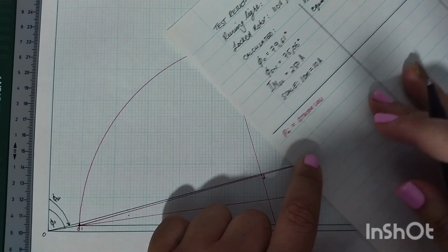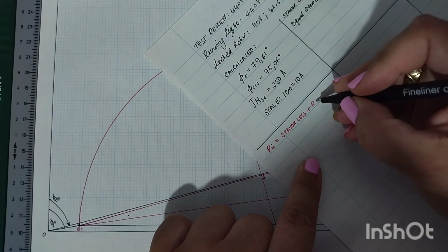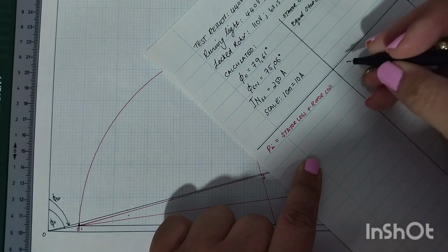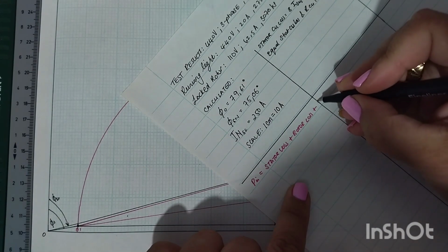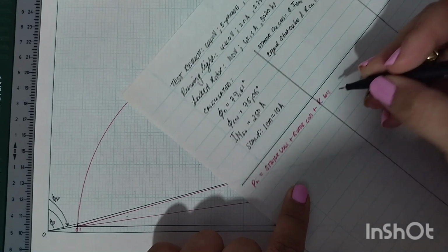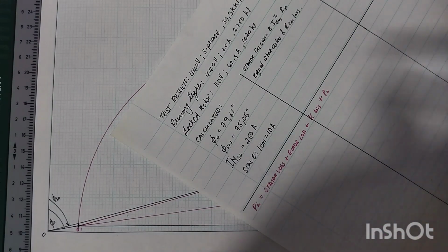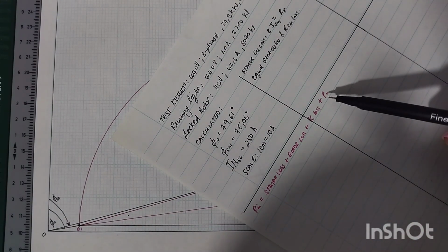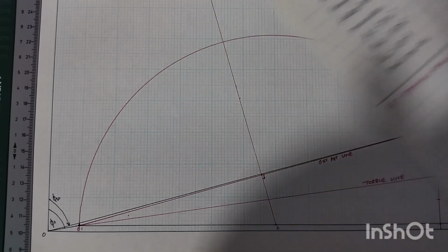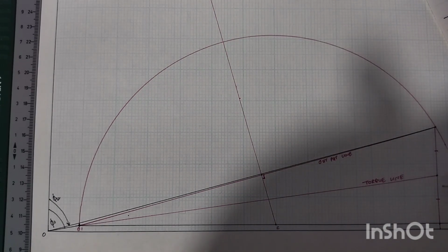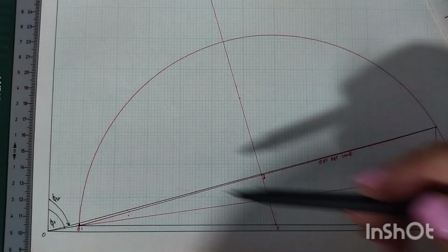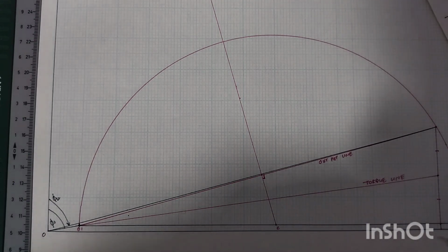And here I just want to remind you of the power flow in a three-phase induction motor: your power into your machine is equal to, I just simplified it here, your stator losses plus your rotor losses plus your constant losses plus your power out. And it would make sense that your power in would be bigger than your power out of your machine. So the distance from your torque line to the perimeter of your circle gives you the torque for any load.